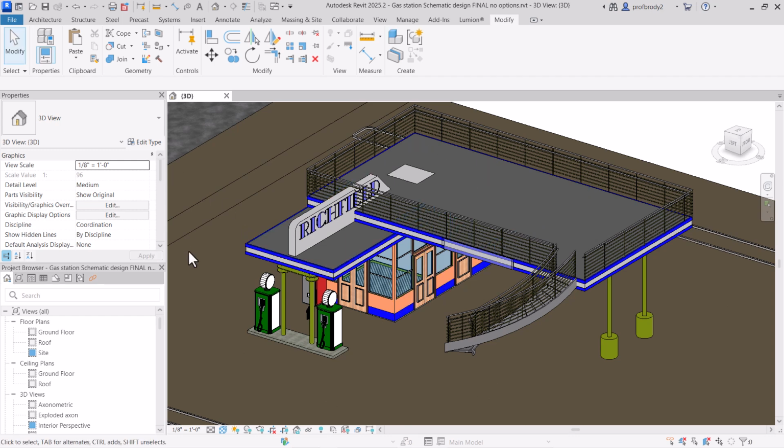So best is to create a parameter in the family and then in Revit in the main project apply that final material. And this is particularly true for objects we get off of the internet, which who knows who made those objects. But when you change the material inside that family, and then try and re-import it, sometimes that re-importation doesn't work. You'll usually see it in Revit, but not always. Again, I'm working in shaded mode, so sometimes the shaded color is just Jim Dandy.